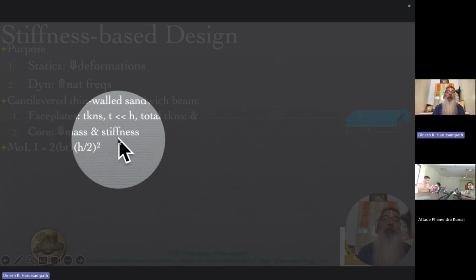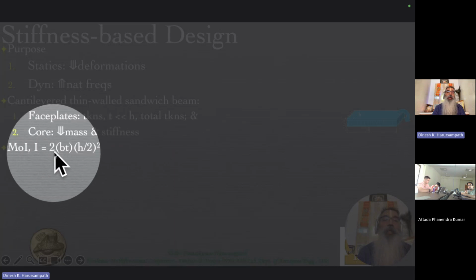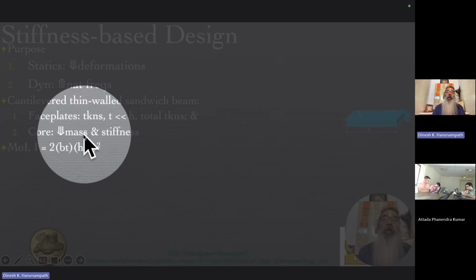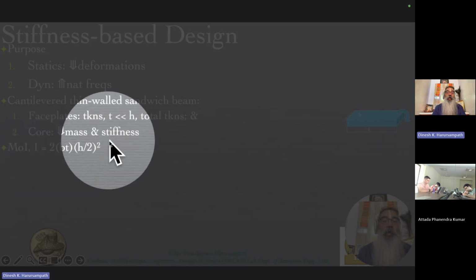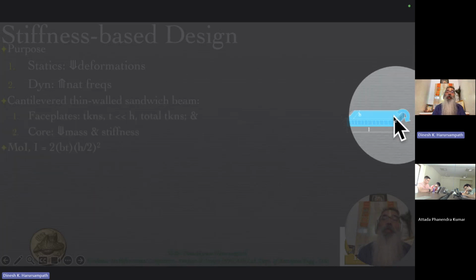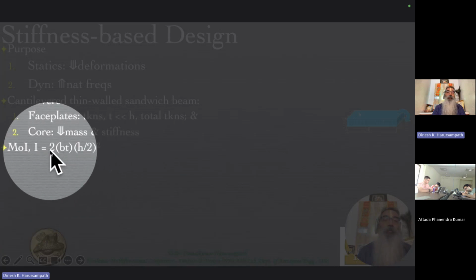So that's the moment arm, which is essentially squared over there. So it's the second moment of area that you're looking at. So you have the area multiplied by the distance of that area's CG, or centroid rather, from the centroid of the overall cross section, and that's what you end up with.